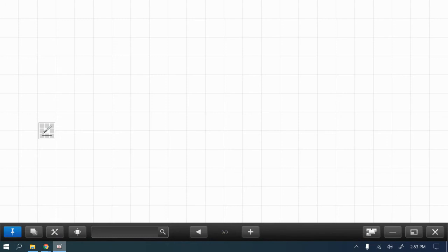Let's look at 23. So 23 is asking what's the suggested thickness for asphalt concrete surface parking area for heavy trucks on a gravelly or sandy, well-drained soil? So for that, we want to look on page 66. So it's full depth, same answer.